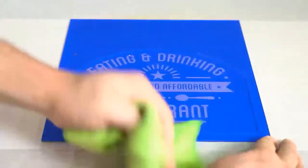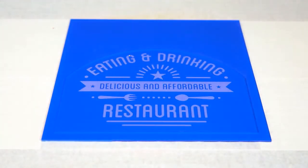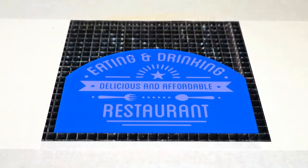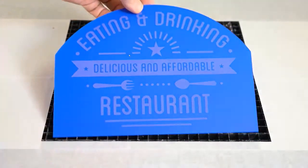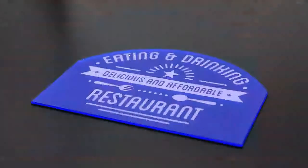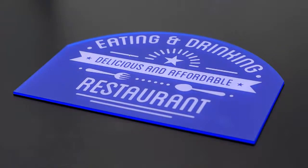After you're done engraving, just take a dry cloth and wipe off the surface if you get any dust on the surface for this nice finished result. As you can see here, it's a nice frosted effect on the surface of the acrylic, producing high contrast, kind of that jewel-toned look. The edge quality is nice and blue. If you hold it up to the light, it's going to shine through it. And so you really do get that effective, nice look in the acrylic. And that's just engraving it. We'll get into cutting here in a few minutes.